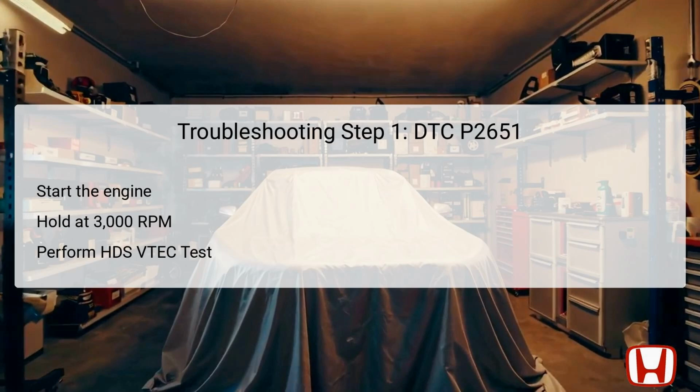Following this procedure, performing the Honda Diagnostic System, HDS, VTEC test is crucial. This test assesses the functionality of the VTEC system and ultimately helps determine if the rocker arm oil pressure sensor is working properly. Gathering this data is vital for the next steps in isolating and rectifying the issue.